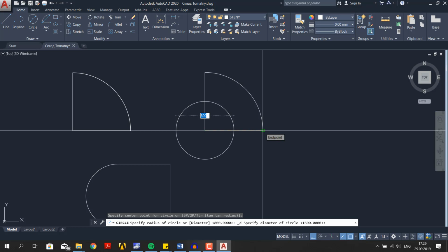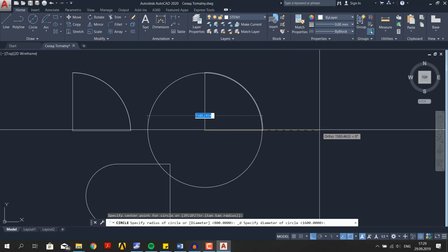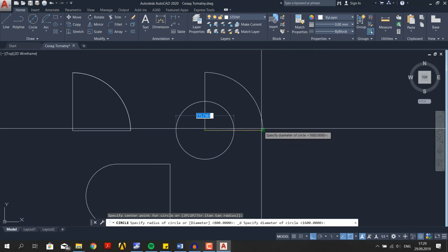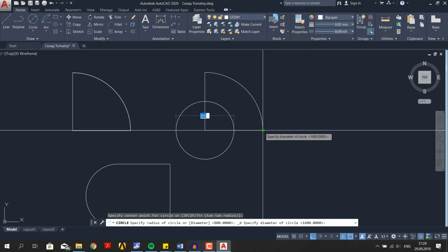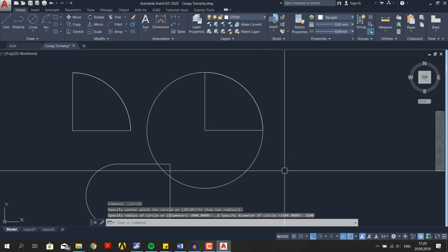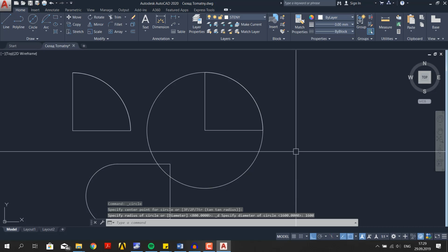Here, although for the second point you will pull in some direction to make a circle bigger or smaller, it will not cross the point you choose. Basically, you select the center and then you just enter the diameter number. Arranging its size with your mouse will confuse you. Just enter the diameter number and that's it. You can check out the others yourself and they are very simple.